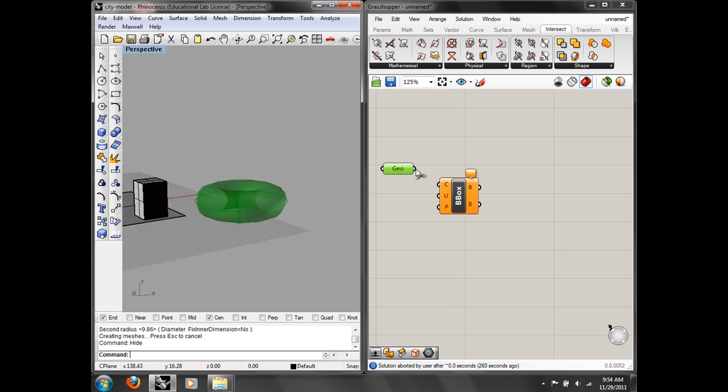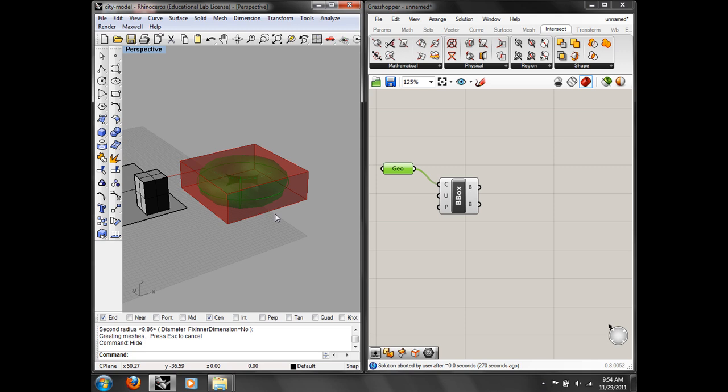But if I plug that in, I can get the bounding box of that torus. Then if I look at the top corner of that, I know how tall the torus is. If I had a cone, or some kind of whoopy thing, I put it inside a bounding box and just measure the bounding box. It's an easy way to get the data out. Okay, so let me get rid of my donut here.